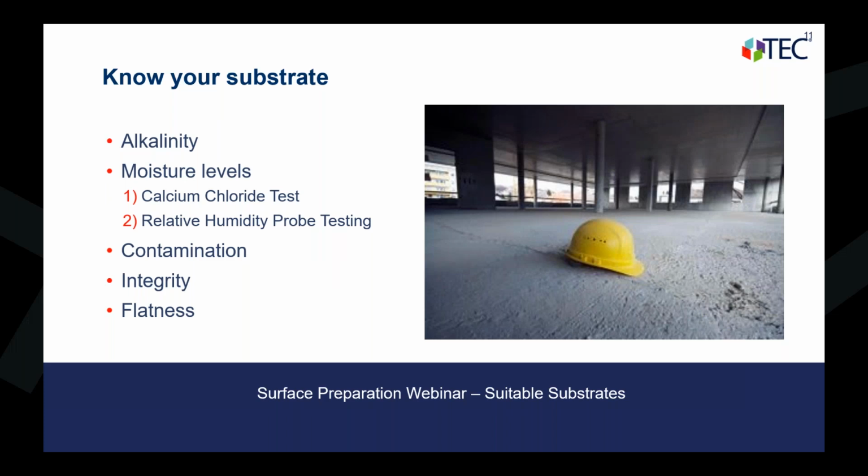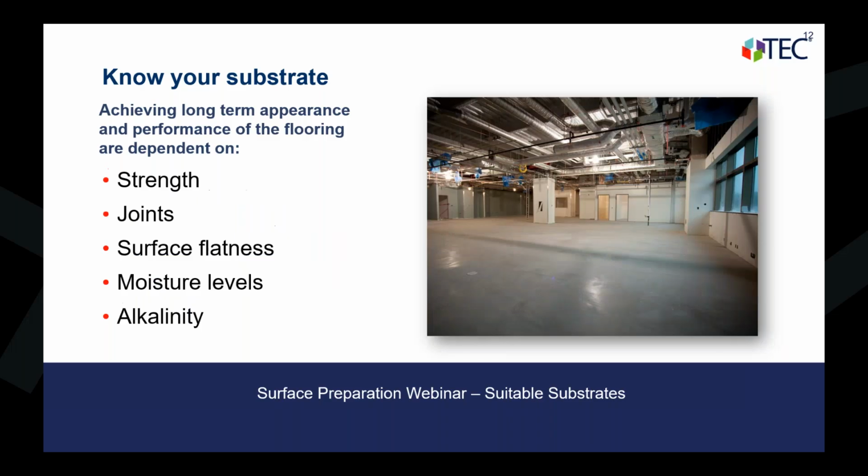If there's any contaminants, whether it's oil, dust, anything that could be on that slab, whether it was a new installation or it's a renovation, we want to make sure all the contaminants are out of there and the integrity of the slab is good, whether for structural integrity and then the flatness. That's one thing that we have to make sure we're covering: our flatness, the strength of the concrete, and again, the moisture levels.